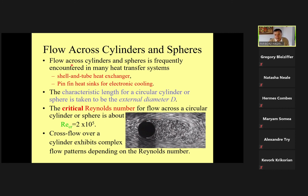Let's read. Flow across a cylinder or sphere is frequently encountered in many heat transfer applications. An example is a heat exchanger: we have a pipe, fluid is going inside, and air is going outside. Pin fin heat sinks are exactly the case that we're dealing with. The characteristic length for a circular pipe is the diameter. Since we know the velocity here, this is the diameter. Even though the fluid is outside, as the characteristic length we use the diameter D of the pipe.